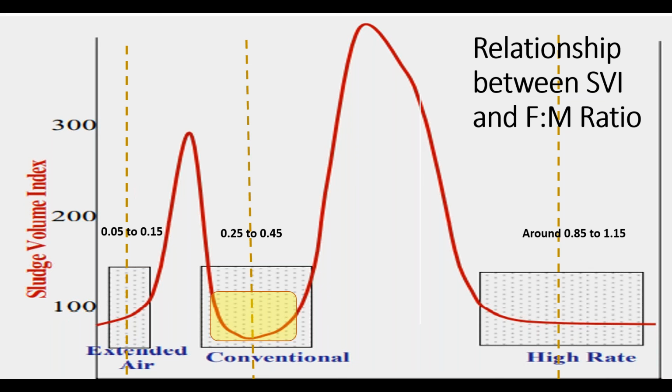And that little yellow spot that I indicated there is probably between like 60 and 120, something like that, on the sludge volume index. And you see that red line shows that that's probably the densest little part where the sludge is going to settle to the smallest amount of space. So you can actually operate your plant based on what produces a good sludge volume index.